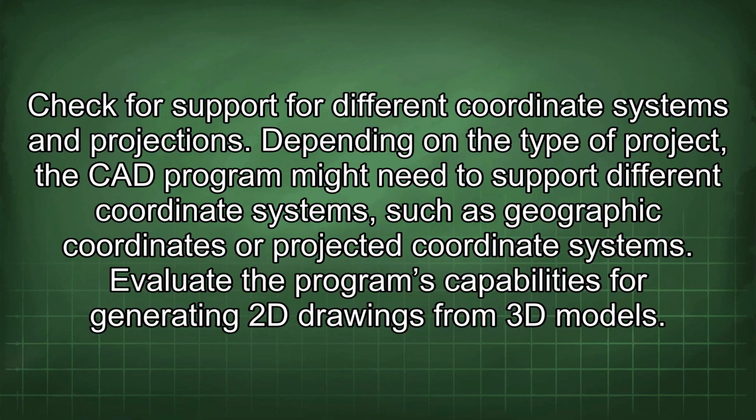Check for support for different coordinate systems and projections. Depending on the type of project, the CAD program might need to support different coordinate systems, such as geographic coordinates or projected coordinate systems. Evaluate the program's capabilities for generating 2D drawings from 3D models.